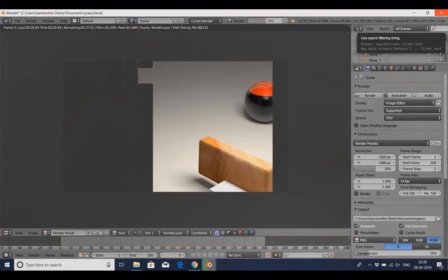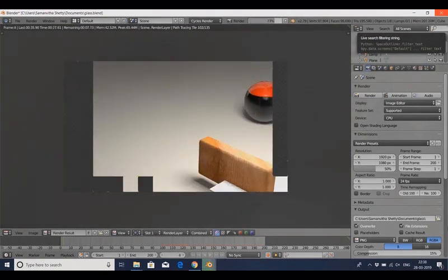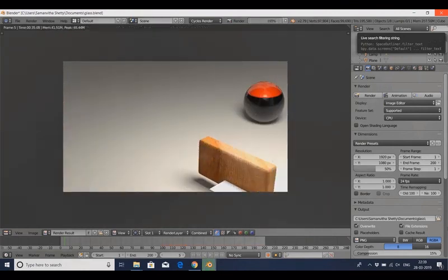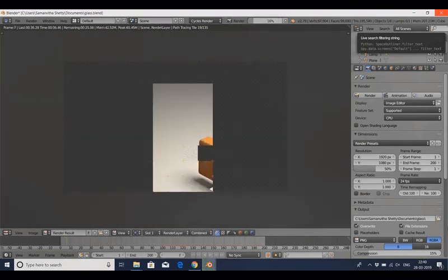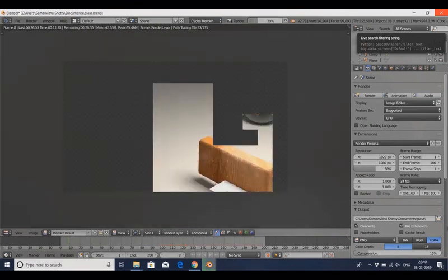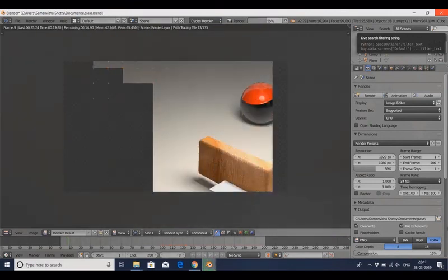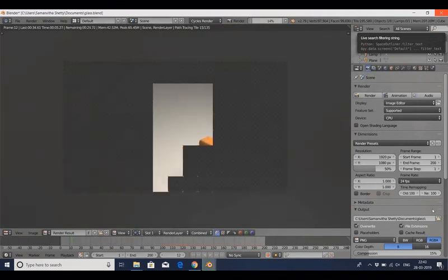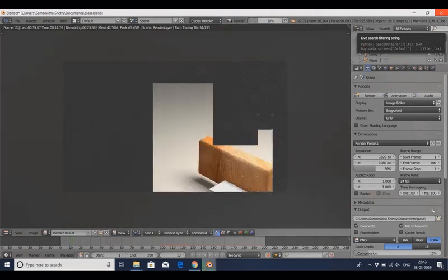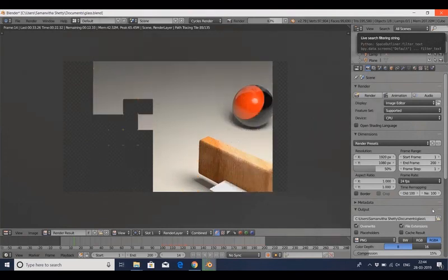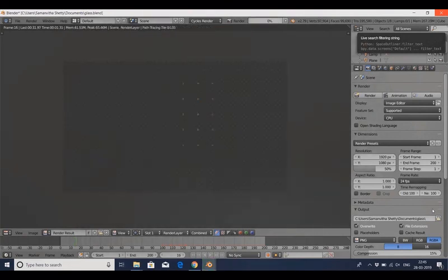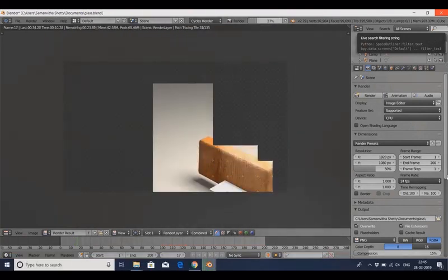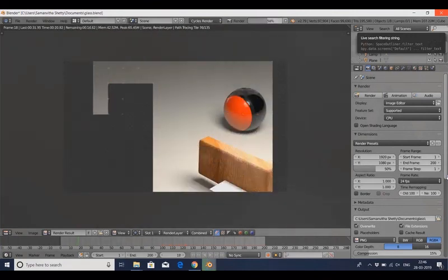Now, bevel the edges of the cube using object modifiers. Select Add Modifier and then press on Bevel. And then click on Apply. Go to the Edit mode and set the size. And then scale it. This will give us the breaking of the wooden blocks and then we obtain the required alphabet which we have used.